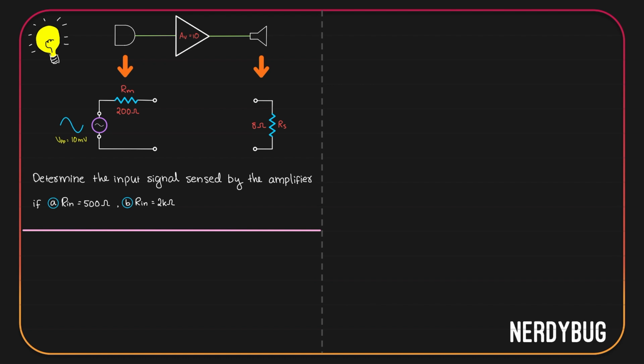We have to determine the input signal that is sensed by the amplifier if the input impedance of the amplifier is 500 ohm and if it is 2 kilo ohm. So our analysis is going to be on the input side. First, let's have a better idea of the circuit. I will take my amplifier. I have also marked its input impedance. It is Rin. Now, this is how we model the mic.